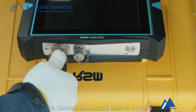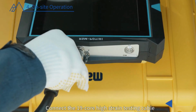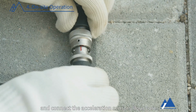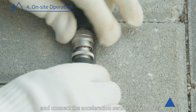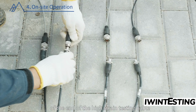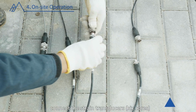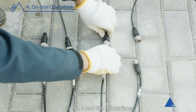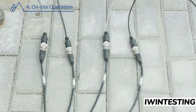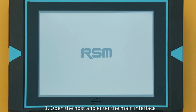10. Connect the host and sensors correctly. Connect the 19-core high-strain testing cable to the interface of the host, and connect the acceleration sensors, 4 cores, to number 1 and number 2 interfaces of the end of the high-strain testing cable. Connect the strain transducers, 6 cores, to number 3 and number 4 interfaces on the other end of the cable, respectively.